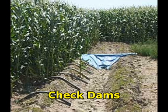Check dams. Several types of canvas, plastic, and metal check dams are available for both lined and unlined ditches. These check dams are designed to block the flow in a ditch just below the point where the water is to be turned out. They can be placed at any location and are not in the way when a ditch needs to be cleaned or rebuilt. Most check dams are adjustable so that the water can be held at some constant level.